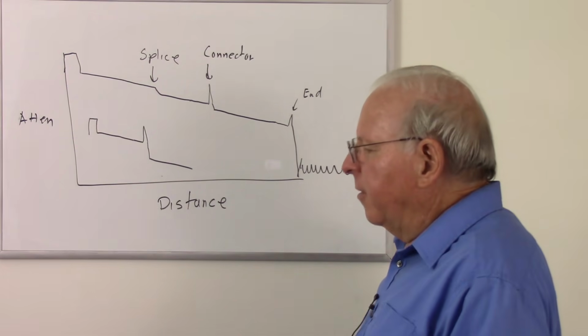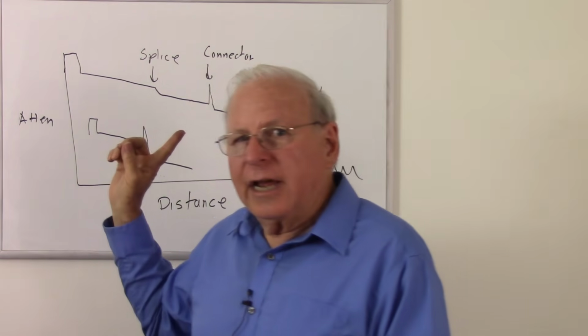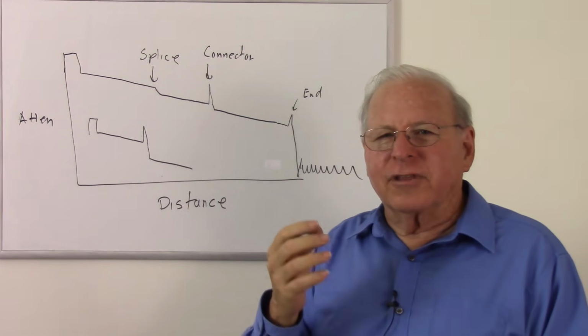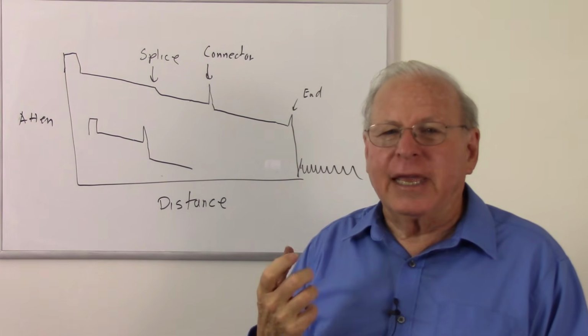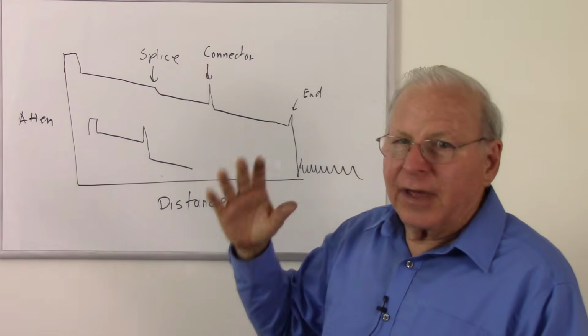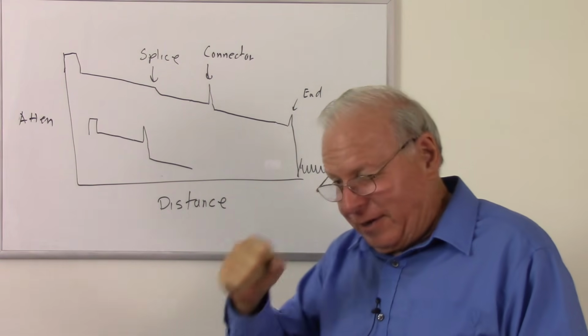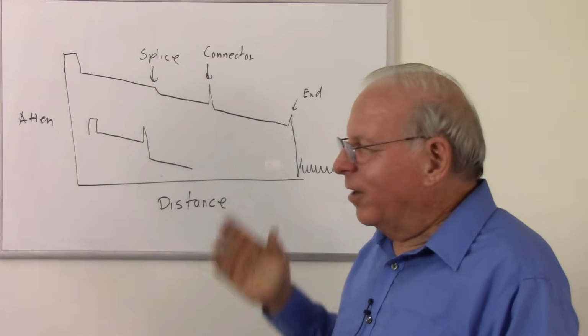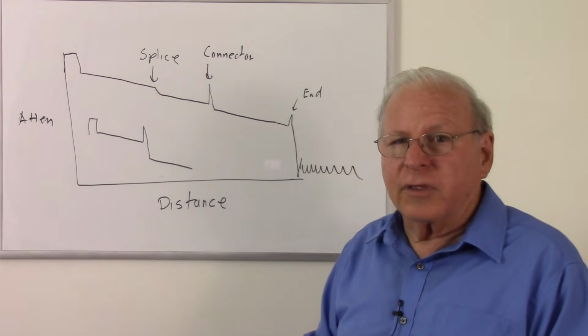But another thing to remember is, what are we shining down this fiber optic? Often it's lasers. What color are those lasers? Infrared. You probably can't see them. If it's 850 nanometers, yeah, you can see that. But 1,000 nanometers, forget it. So I don't see anything in this cable. I don't see anything anywhere now. So you want to be careful about that. Remember that you're working with lasers.